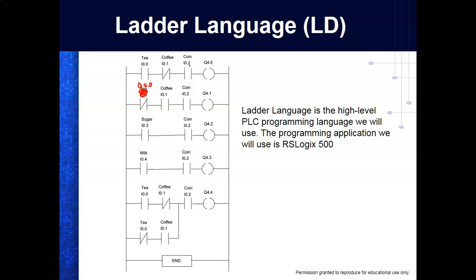If we give an input instruction the same address as a coil or an output, then it's controlled by that. If we give this symbol the address of an input port, then it's going to be controlled by a push button or whatever. And we'll get into that. But this is ladder language, guys. Here in the United States, probably 95% of the programs written for PLCs are written in ladder.